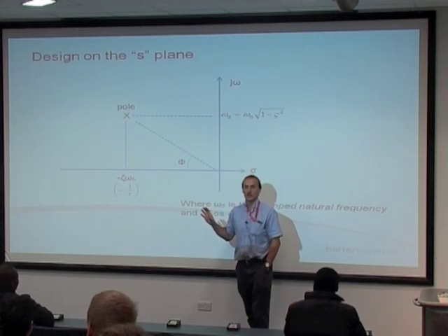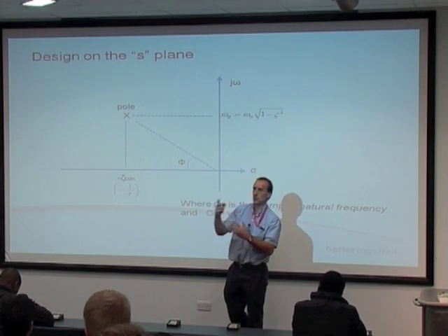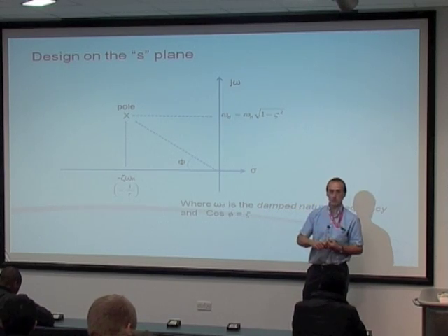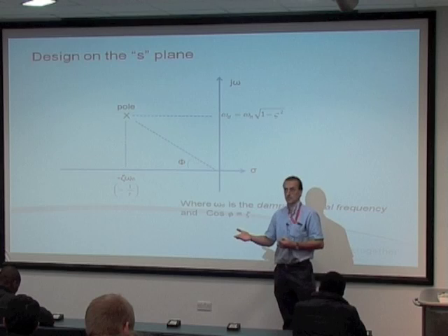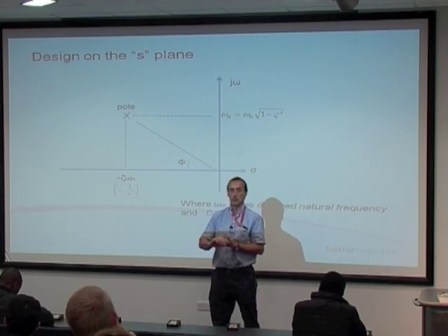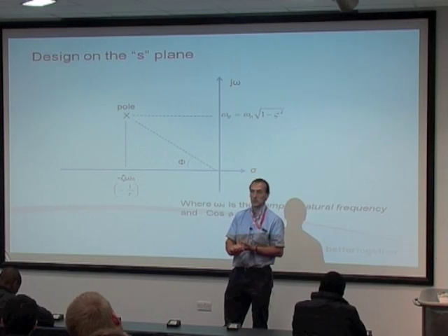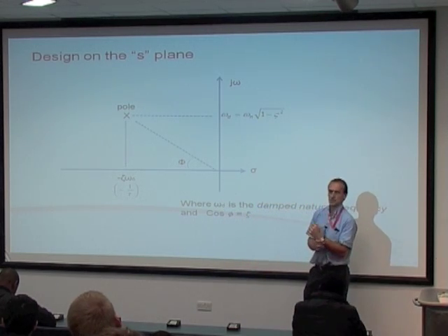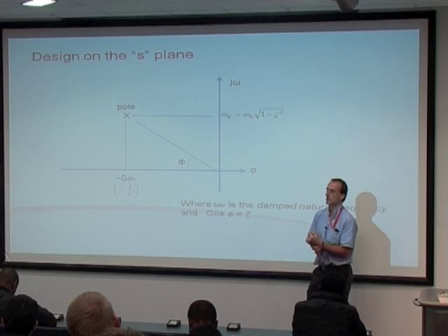3 time constants. Yeah, if you recall first order responses and the definitions, after 1 time constant, the system will reach 63% of the final value. After 3 time constants, it's 95%. And what's the other definition of settling time that we discussed? Yeah, 5 time constants, which is something like 99.5% of the final value.